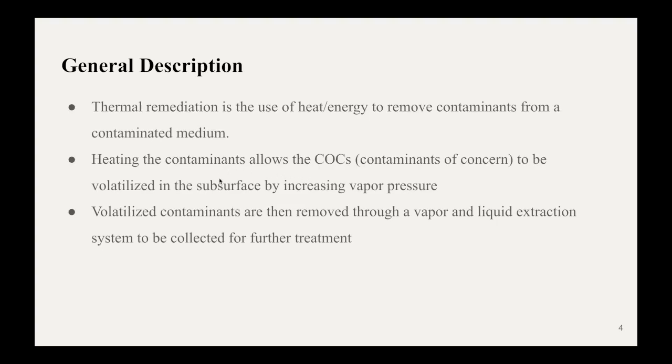For all types of thermal remediation, there will be a vapor and liquid extraction system set up so that the volatilized contaminants can be safely collected for further treatment, whether it be using some sort of granulated activated carbon or maybe some sort of air stripping to absorb the COCs.